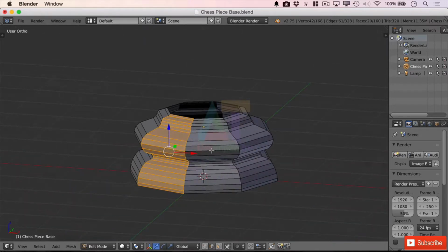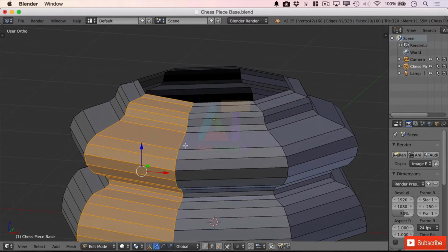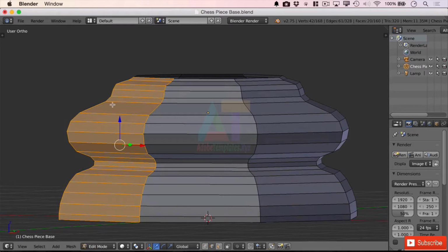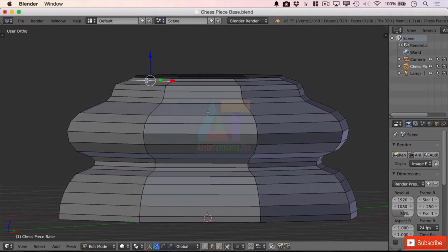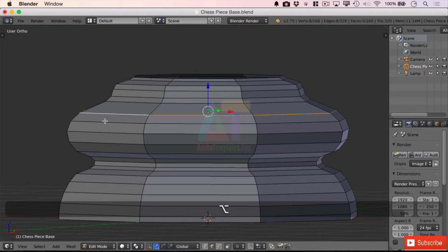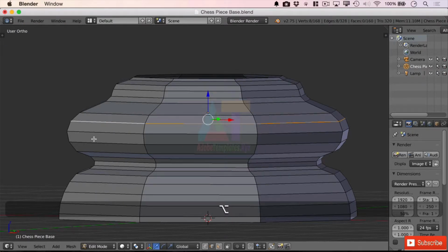The final set of edge loops is just to make sure this isn't quite so curvy. And usually the best way of doing that is, if we look at sort of a profile running down here, to remove the ones in between the points of inflection. So that would be this edge loop round the top, not the very top one, but that one there. Then it's got a point here. Then these two can go, leaving that one. These two can go here, leaving that one.